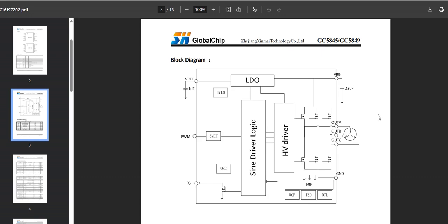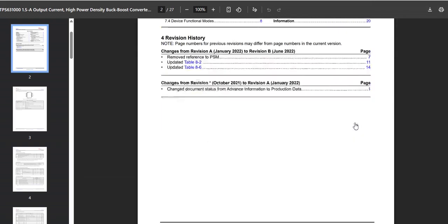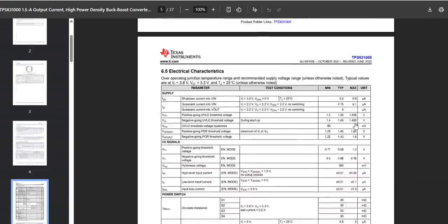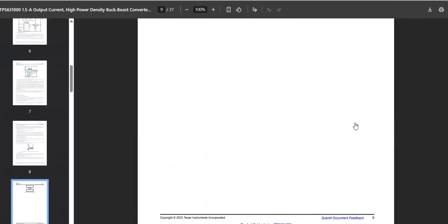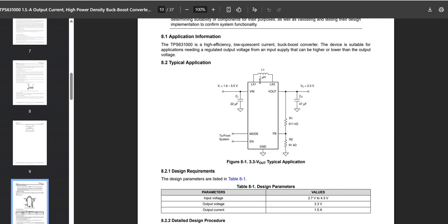Obviously inside of the IC we cannot change, but the outside components, as I showed you here, these two resistors. By changing the values of a few components around it, outside this IC, outside this box, we can change the required output for us.